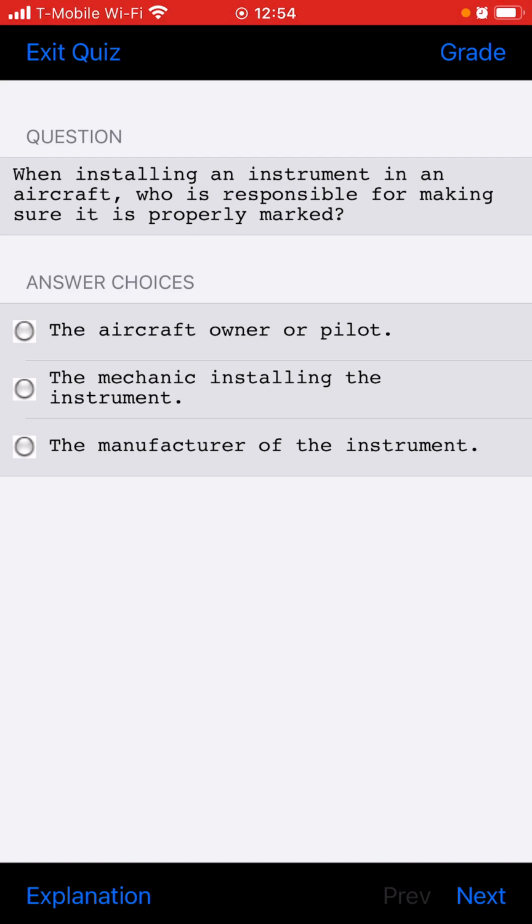What conditions should a mechanic look for during a regular inspection of the exposed piston section of a landing gear? Cleanness, evidence of damage, proper extension. So if there's evidence of damage, you've got to do a replacement.